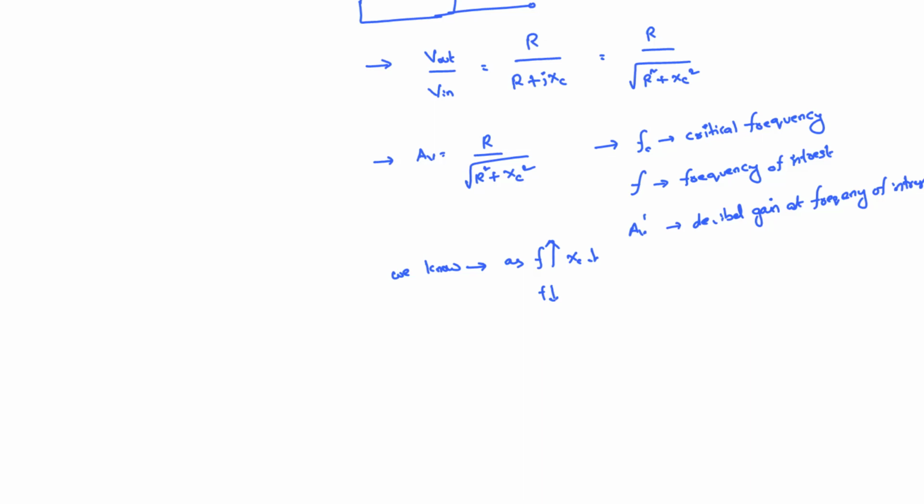As you know very well, a very important thing in the capacitor is that as the frequency increases, the reactance of the capacitor reduces. As the frequency reduces, the reactance of the capacitor increases, by the formula Xc is equal to 1 by 2 pi fc. And from our earlier formula, the cutoff frequency f is equal to 1 by 2 pi RC. From there I can write R is equal to 1 by 2 pi fc.